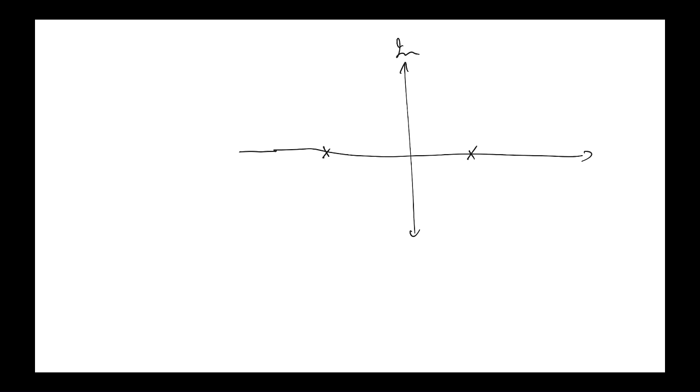One of those controllers was just a lead compensator, right? And the point of the lead compensator was to try to, so if we look at a situation like this and a controller that just has a constant gain, then we get a root locus plot that looks something like this, right, where they move together and split apart as we increase the gain, all right?